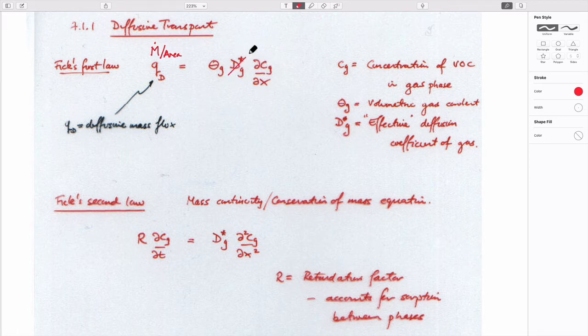This is a gaseous diffusion coefficient. I guess it's written down below. It will always be in meters squared per second as units. And the star refers to the fact that it's modified. It's modified because instead of the straight diffusion coefficient, which would get you the smell of smoke from a smoker sitting in a room, you could imagine the room being filled up with sand, an aquifer, and it has to wind its way through the pore space. So it's modified by the tortuosity of flow.